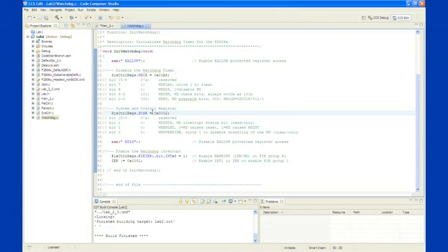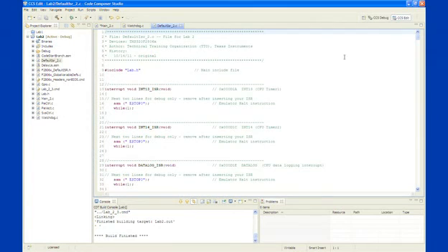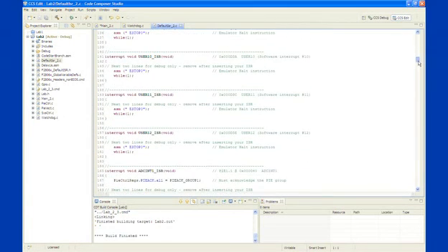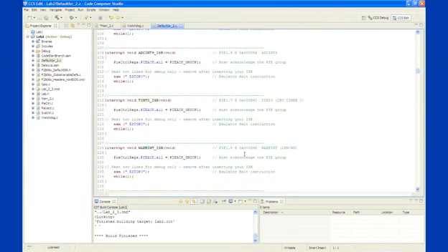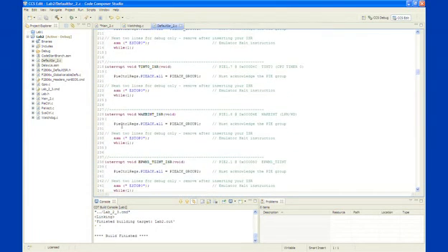And what's going to happen is when it generates an interrupt, we will look at defaultisr.c, and there's a section down here, 1.8, which is right here. And that's where our interrupt for the watchdog will go, at the wakeint_isr. Here you'll find there's an ESTOP instruction. And what this basically does is it's equivalent to putting a breakpoint in the ISR right at this point here.